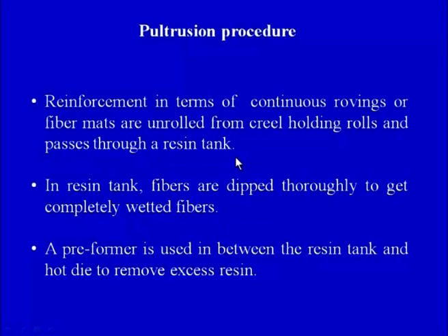So first the fibers will come, and these will then go to the resin tank. In the resin tank, fibers are dipped thoroughly to get the completely wetted fibers. So first of all the fibers will be coming, they will be going into the resin tank, and from the resin tank they will be picking up the resin.